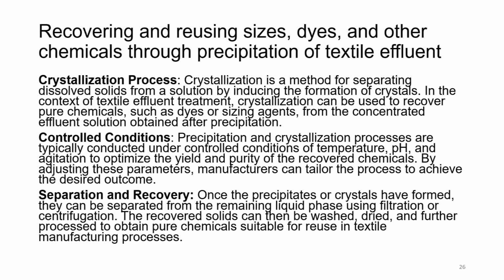Crystallization process. Crystallization is a method for separating dissolved solids from a solution by inducing the formation of crystals. In the context of textile effluent treatment, crystallization can be used to recover pure chemicals such as dyes and sizing agents from the concentrated effluent solution obtained after precipitation.